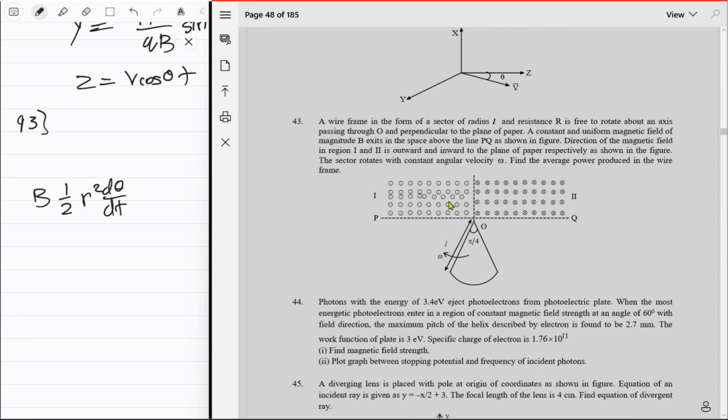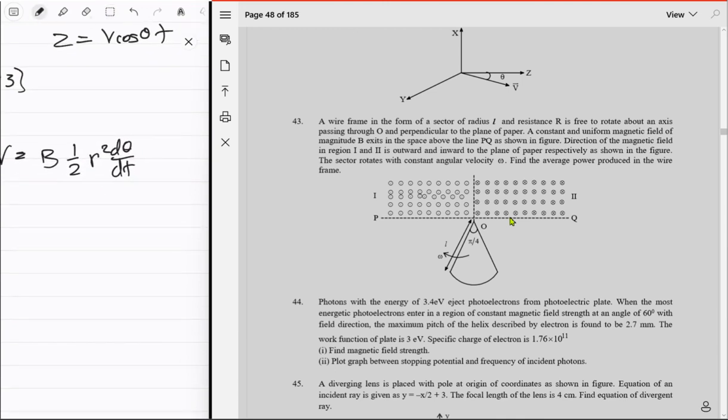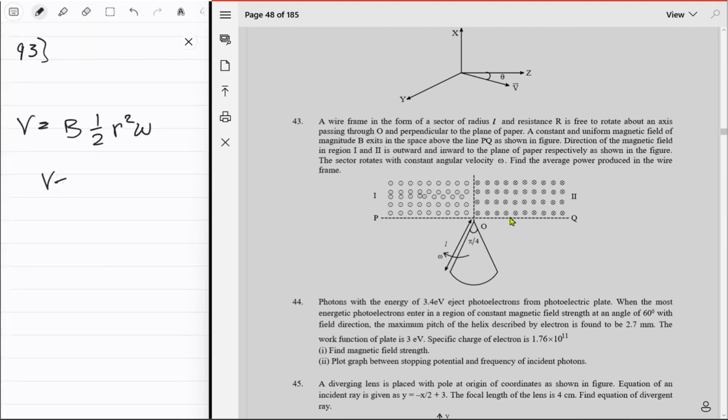How strange, what is its resistance given as? Total resistance R, whatever it is. So this is our flux and the voltage will be constant. And upon just omega, so yeah, okay, this is actually kind of constant. So our voltage is just B R squared omega upon 2 as it goes into this, right? And yeah, throughout, current is there in it. Then now when it goes like that, okay, then the current reversed, but it's still there, right? That current is still there, of course.